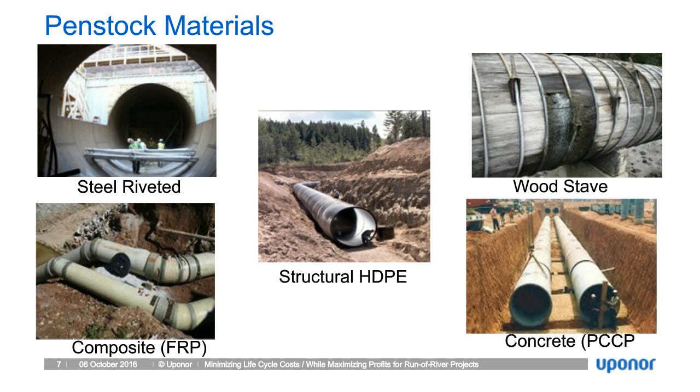The last picture here is the structural HDPE, or Weholite as we call it. This material was developed specifically for low pressure, high volume applications, such as run-of-river applications. The value of this structural HDPE pipe comes from the engineering marriage between the HDPE characteristics extruded into a specific profile. The material characteristics are very robust, but the profile really lends to the structural integrity of the pipe structure, and we'll get into that a little bit more. So I just wanted to touch quickly on the common materials that are now out in the market space.